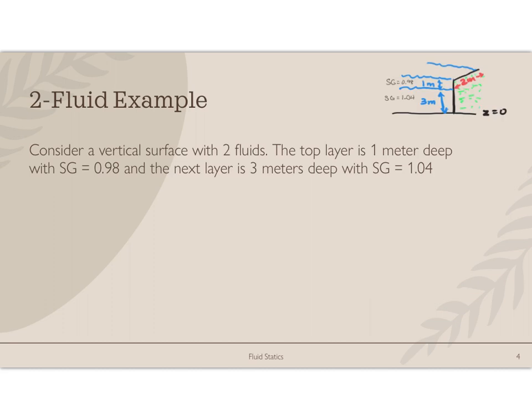In my drawing, what you can see is the two different liquids, and then there's this wall over here. This is a solid wall, like built into the dirt, something like that. So the wall is not subjected to atmospheric pressure. We want to find the absolute pressure on this wall, so we're going to need to include the atmospheric pressure. A lot of times we'll do it by indicating where the atmosphere is being applied with a little upside down triangle.